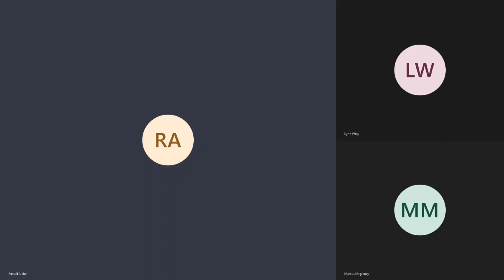You can't have any gaps in it. Your polygons gotta butt up exactly. And it has to be a single shape file or a single feature class. You can't have a road shape file and then a building shape file and then all the other ones separately. They all have to be as one. That does not mean you can't digitize them individually and then do overlays, okay?